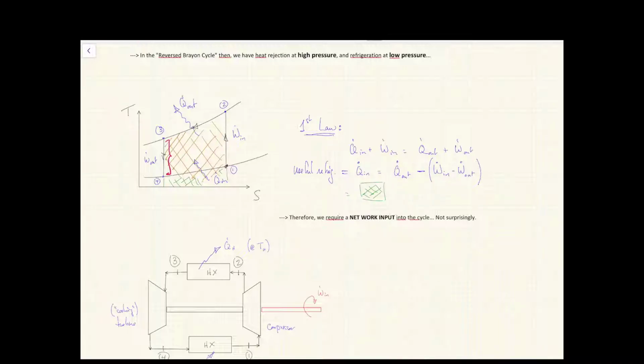In other words, simply throttle it back down, because the entropy increase would be such that by the time we end up at the pressure that we want, the temperature would actually be significantly higher than what we want here. That's what we would lose if we were to run this thing with a valve instead of using a turbine.